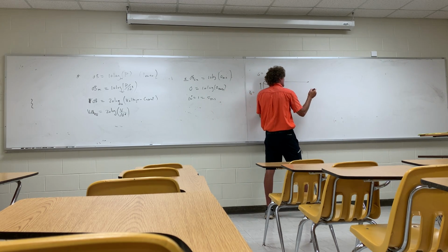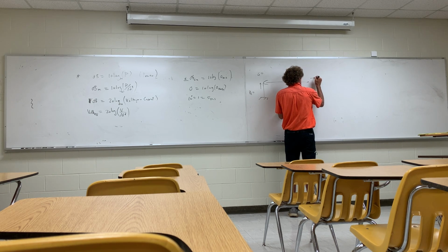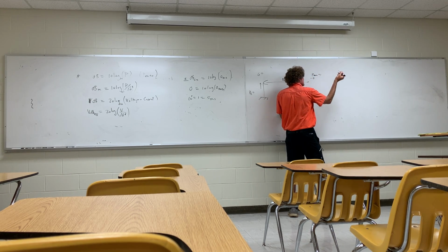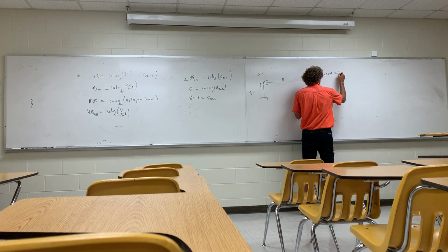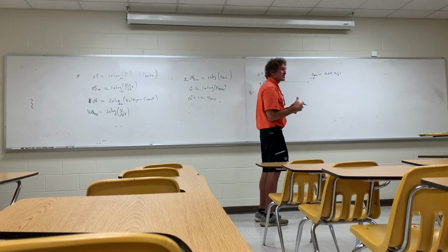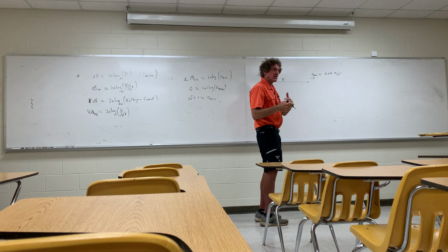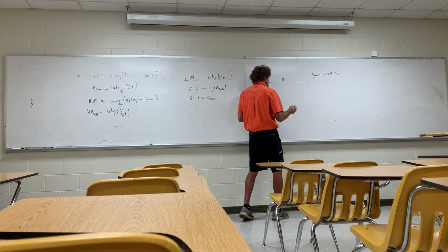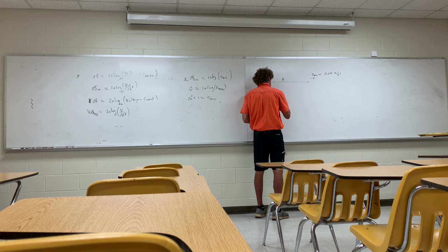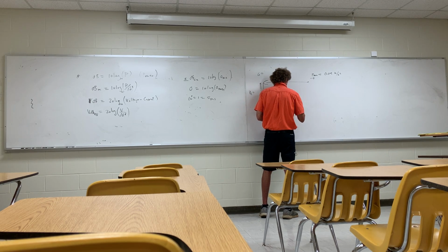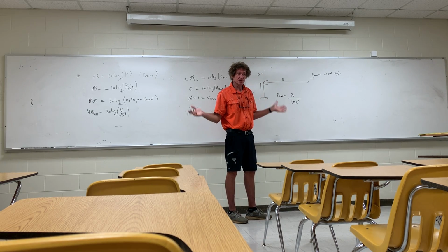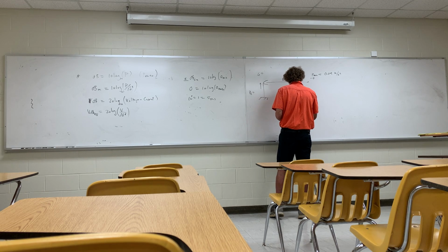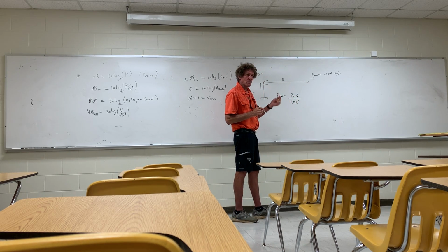Alright, so you're at a range R and you have an average power density given, the average here, and it's 0.04 watts per meter squared, alright? Now, this just checks to see if you have a good understanding of radars, or really power transmission in general. We know the average power density from any kind of antenna will always be the total power transmitted over 4 pi r squared. That's where I always start. That's isotropic, no gain, no focus. Then you multiply by the antenna gain, and that's the power density at the point, right?